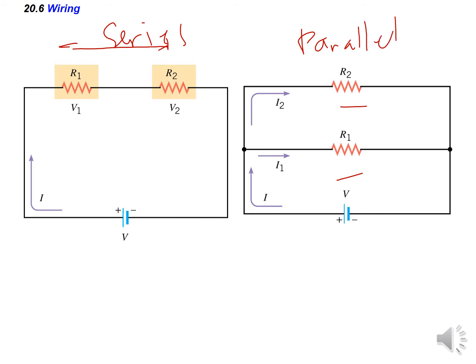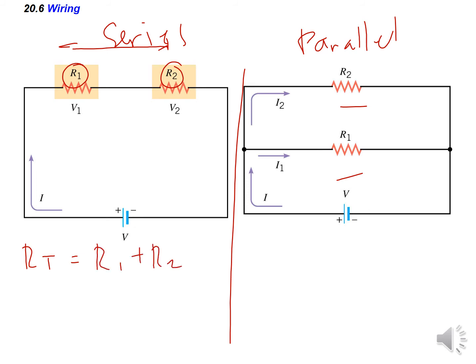In series connection, we have different properties. So what is the value of the voltage or potential difference, the total resistance and current when it comes to series and in parallel? In series, to get the total resistance, we have resistance 1 and resistance 2. The total resistance, or equivalent resistance, is simply the sum of all the given resistances. If there's additional resistance, for example R3, you just need to add R3. Again, total resistance is equal to R1 plus R2 plus R3.